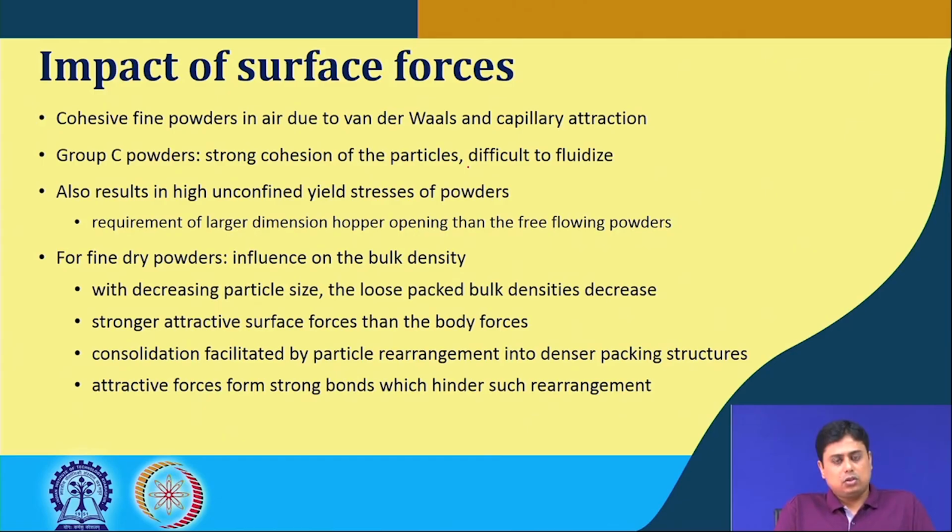This is also the reason why the Geldart group C particles exhibited strong cohesion and were difficult to fluidize, because of this attraction and the fine size of the particles. These surface forces also result in high unconfined yield stresses of the powders, which means a larger hopper dimension is required for storage and discharge of these fine particles than for free flowing powders.